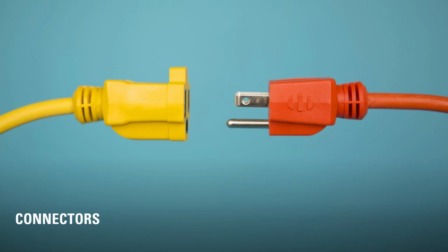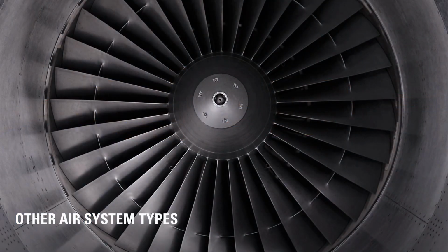There are different connector types: duct connectors, pipe connectors, electrical connectors, cable tray connectors, and conduit connectors. Choosing the correct connector discipline is absolutely critical. Once a connector is placed, its discipline cannot be changed without deleting and recreating it.